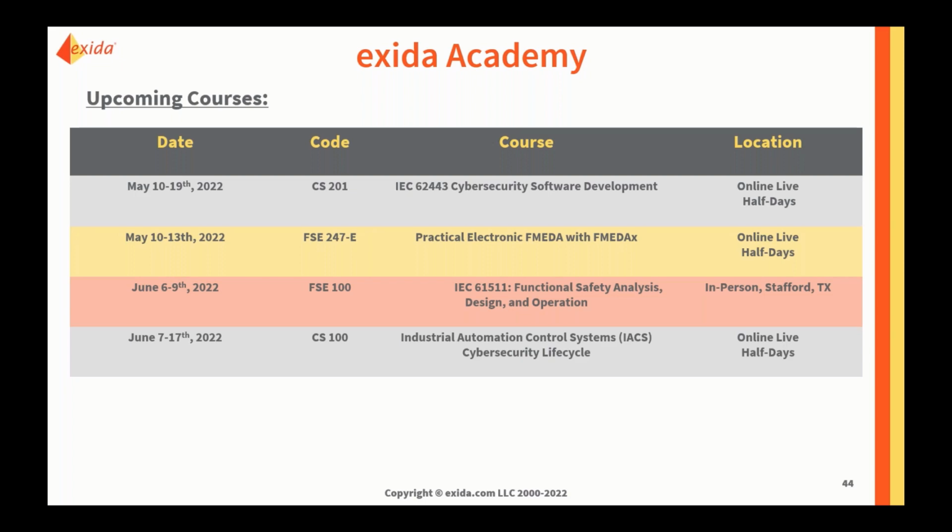And then finally, can we say that a BPCS has a continuous demand for control function, but could have low demand for safety function? Now, this is all down to where in the sequence of escalation the basic process control system falls.